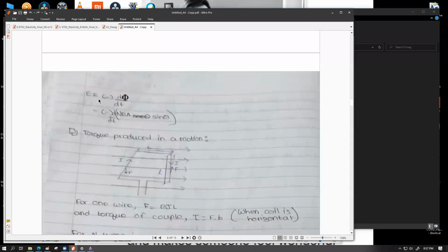Motor means we're going to feed electrical energy into a device, an electric motor, and kinetic energy will be the output, which means you're going to be getting output torque or turning effect of a shaft. Vice versa, we're going to physically rotate the coil inside a generator from the outside, from a prime mover, which can be a diesel engine, petrol engine, or a wind turbine, water turbine, or a human hand, for example. That rotation produces cutting of field lines and electricity can be generated. So we have to work with both of these variations.